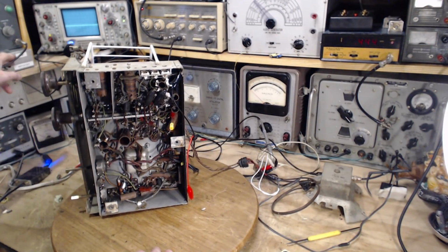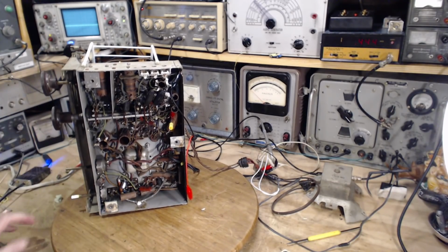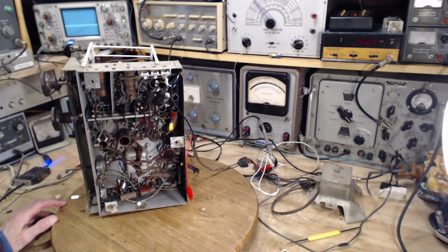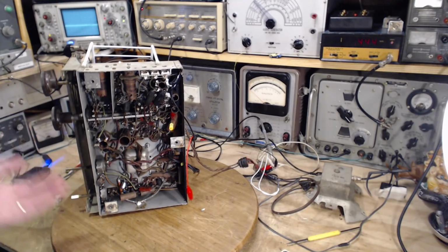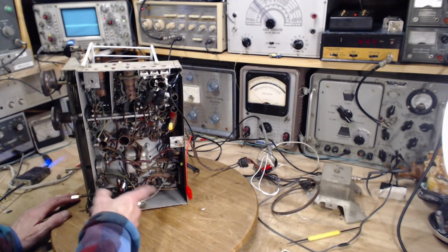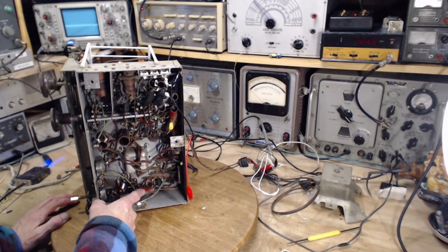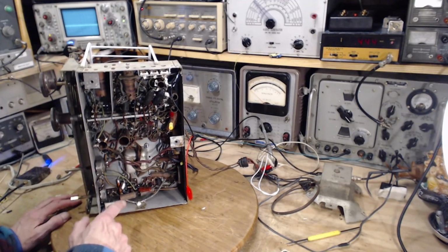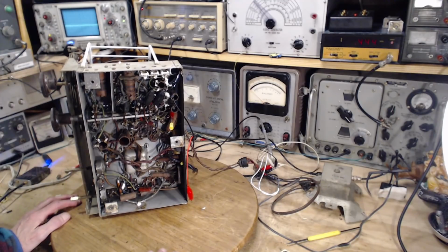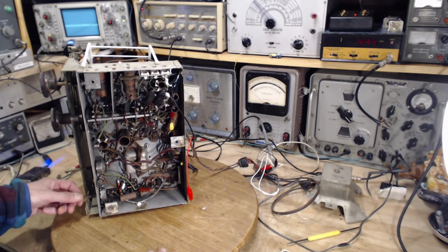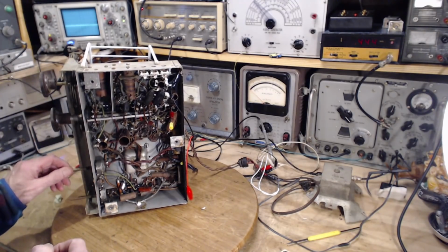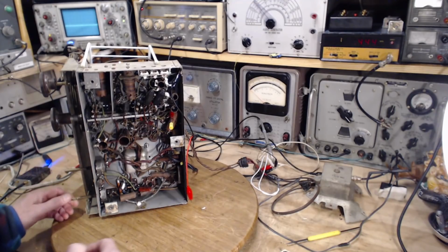Okay, back on. So what I'm hoping to do here is get the very same distortion coming out of the radio. That's what I'm looking for, and then we can continue hunting in the audio circuits, which are all down here. So I already got one capacitor changed, another one I did right here, and we have potentially a tube in there that's not going to do the job as well as maybe it could. No sound at all. Okay, so we're going to hook up.